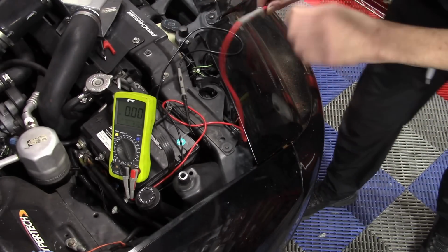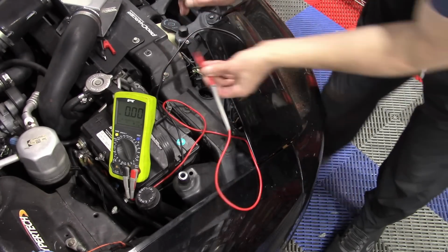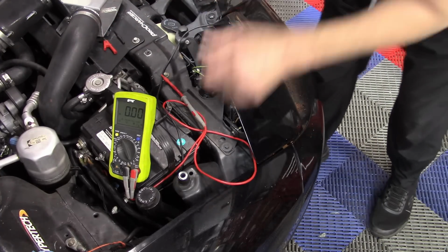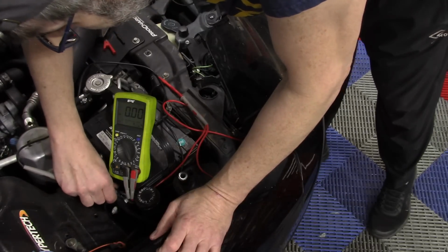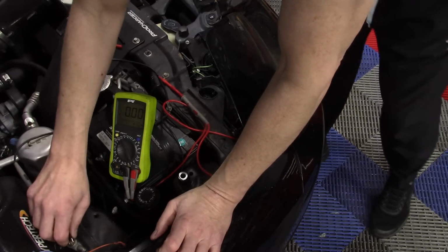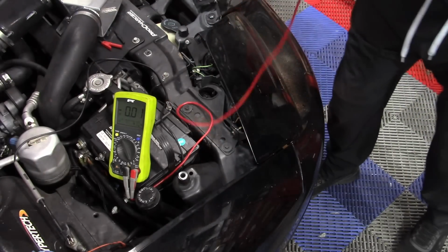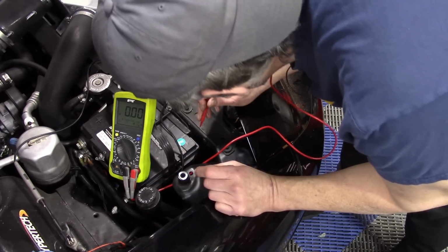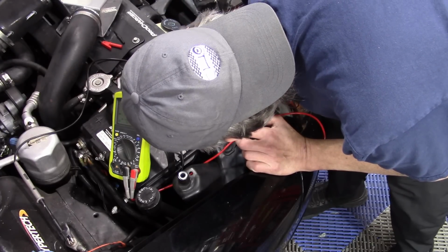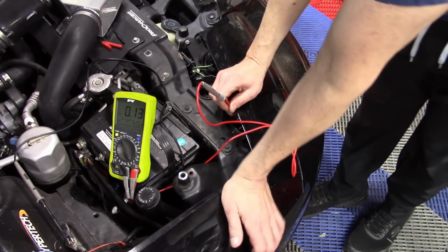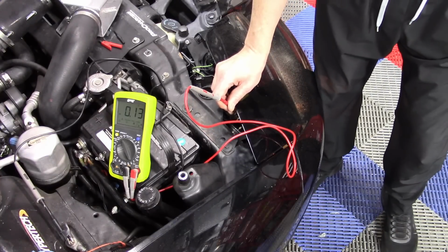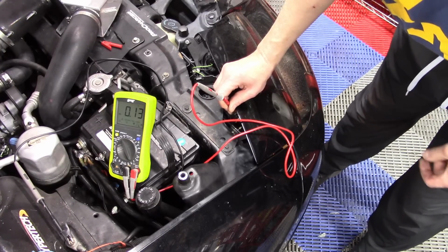Well, what our directions say is we want to check the ground side, okay? So we can totally do that. We're going to take our negative lead, and just like we showed, go over to the negative side of the battery on one lead. The other lead we're going to put on the negative for our point after the bulb. There should be no voltage there. And as we can see, we only have 0.13 volts. That's pretty acceptable, pretty minimal. So that's certainly not where we're losing voltage.